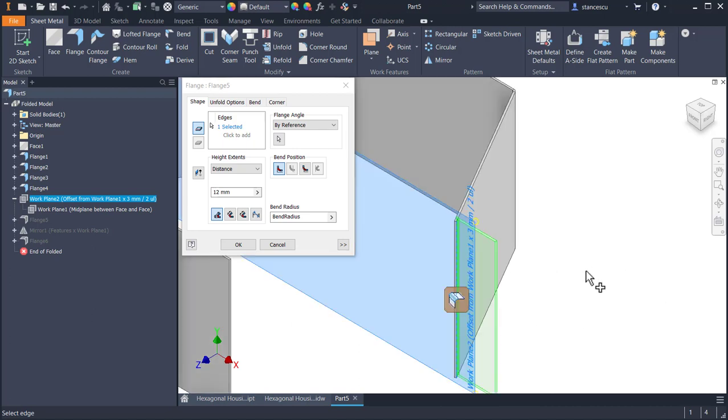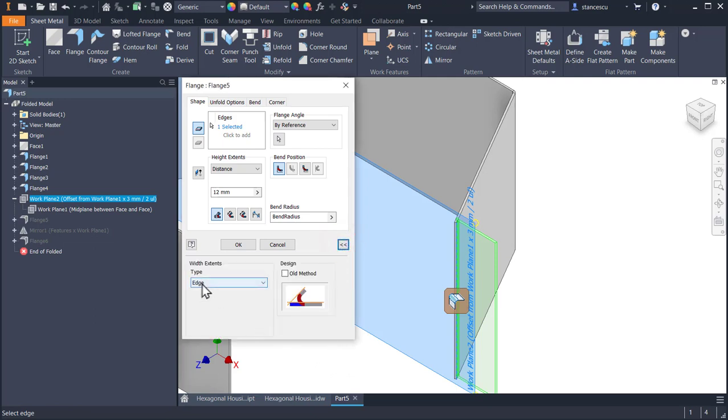So I can edit everything, not like in AutoCAD, where you place a dimension and it is a result, not a cause, that dimension. What to do here? Well, I select this more option. I select width. We know this procedure from my previous tutorials.